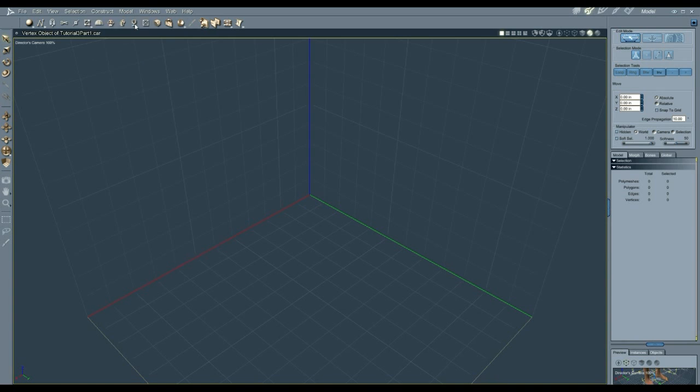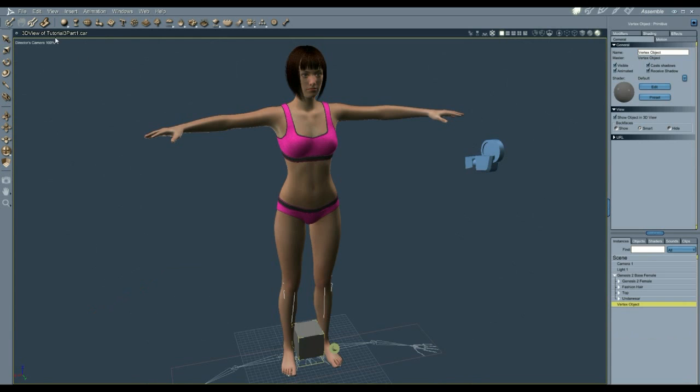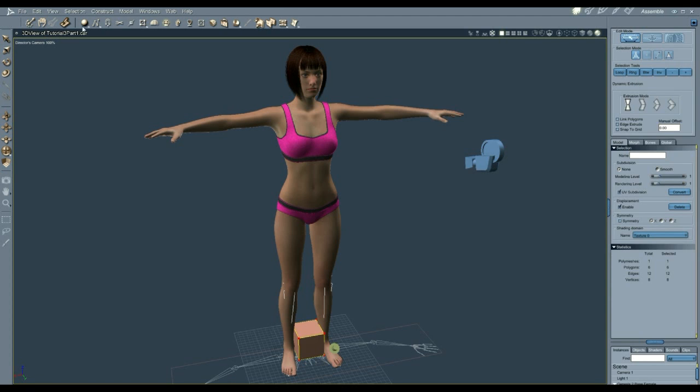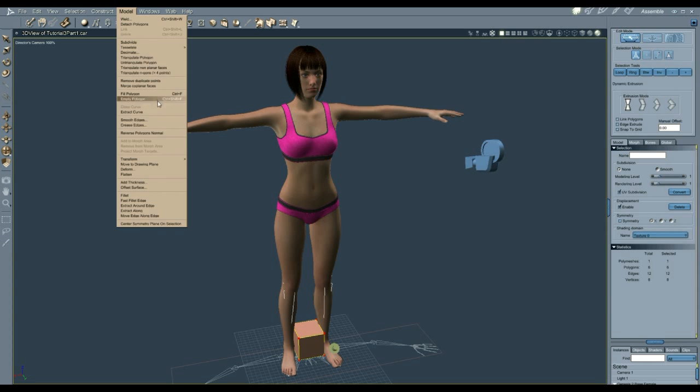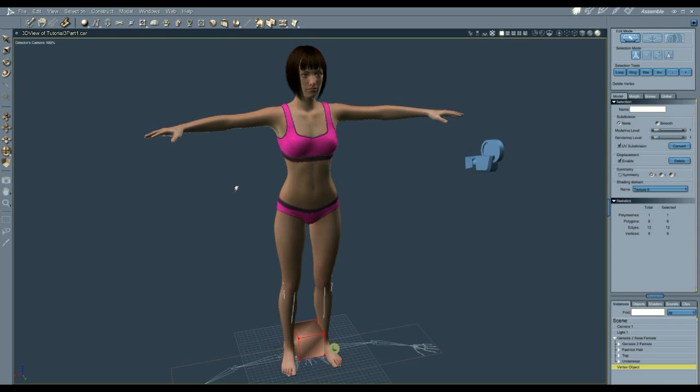My recommended average size of the final mesh will be 1/2 to 1 inch. Working backwards from a final 3/4 inch or 2 centimeter mesh size, double that 3 times and get a starting cube of 6 inches. Subdivide 6 to get 3, subdivide 3 and get 1.5, subdivide one more time, and in the end we'll get 0.75.